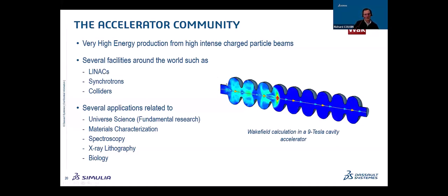Several facilities around the world can also be analyzed using this kind of technology. And that's really key to analyze, especially in the design phase, the higher order modes, which can be generated using the Wakefield solvers inside these cavities, to have a clear idea of how the design has to be performed in order to select the right modes and phase that you would need to keep the acceleration process going for your particles.